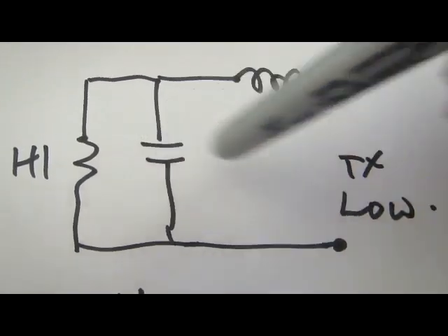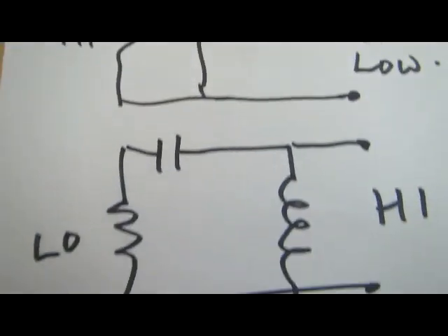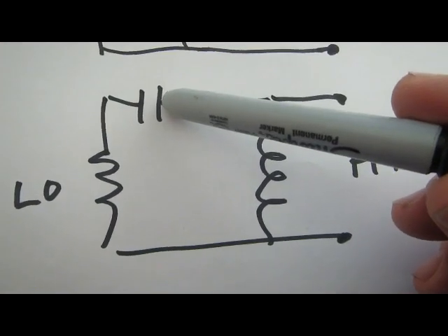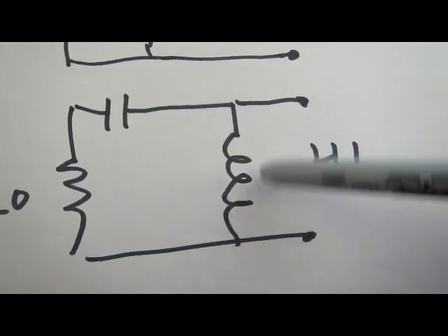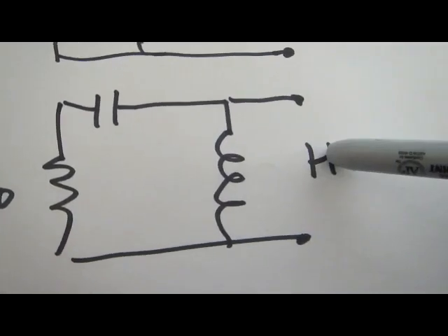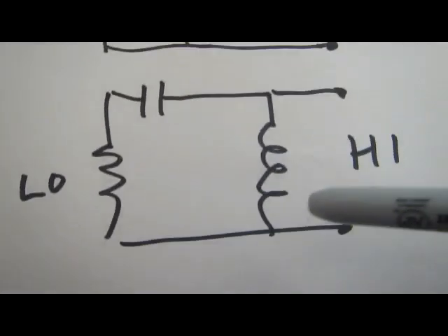So high sort of goes parallel to series. The other way around is when it's a low resistance. We put it in series with an intentional reactance, and then we tune it out with what's more or less a parallel circuit. So it's like series resonance to parallel resonance. These are the two ways round to it.